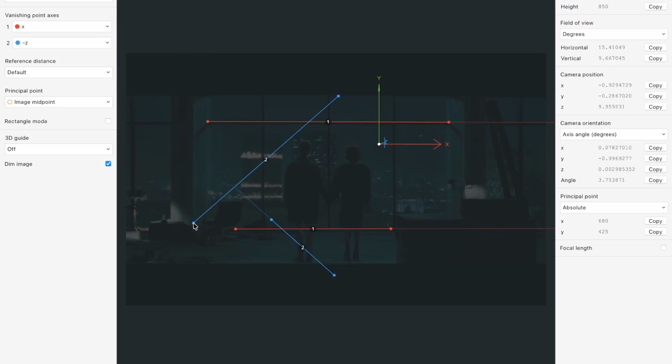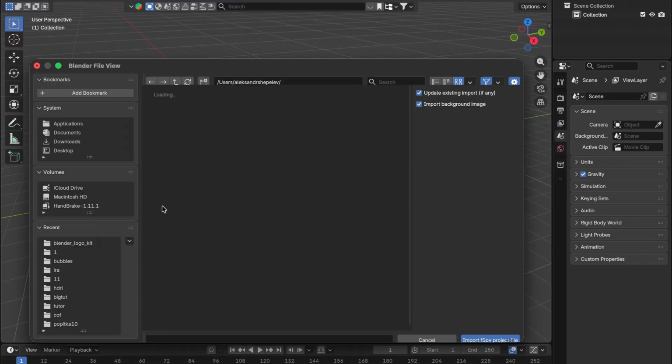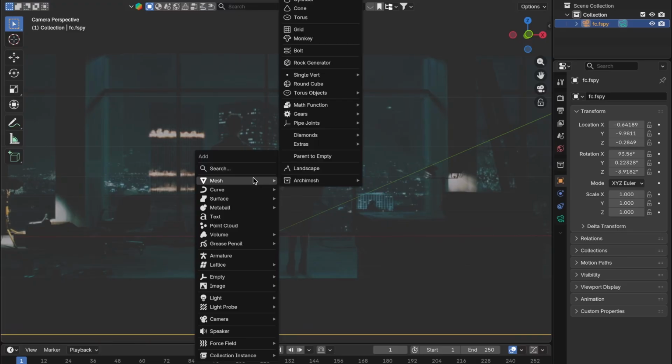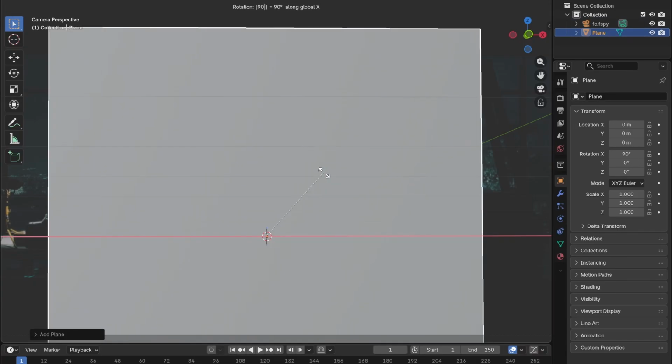For this we will select our main axes. These are the x-axis and the z-axis, and we will position them along the most suitable planes. In this case, these are horizontal lines on our window and the vertical columns, and fSpy will automatically determine the focal length, and then we will be able to import this scene into Blender and, strictly speaking, start working with it.